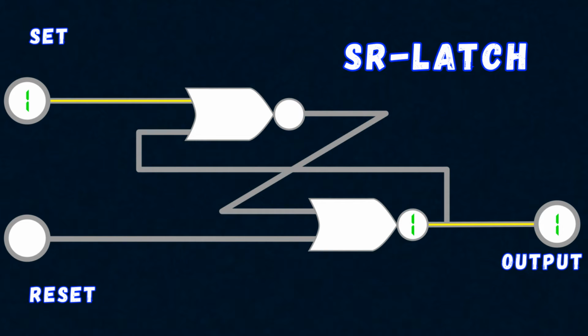In addition, this 1 will be sent to the second input of the first OR-NOT gate. This will not change the result, since if both inputs of the OR NOT gate are 1, the result will still be 0. But even if we now disconnect the set input, the result will not change. The first OR NOT gate will still output 0 at the output, forcing the second OR NOT gate to output 1. You may ask, where does the signal come from in the system when we don't apply anything?